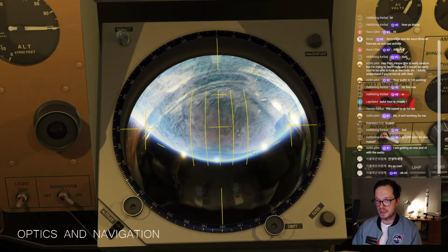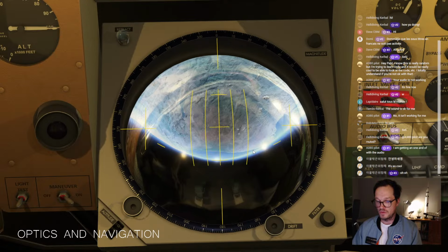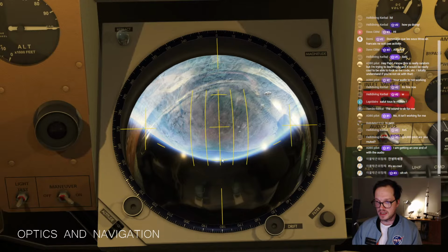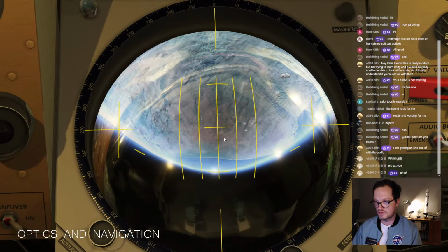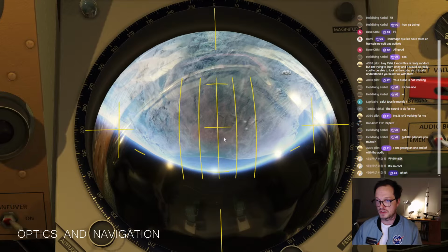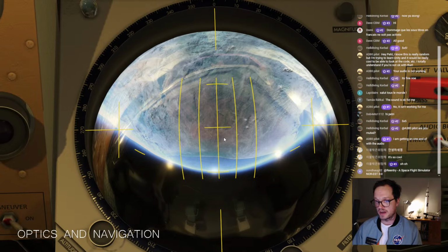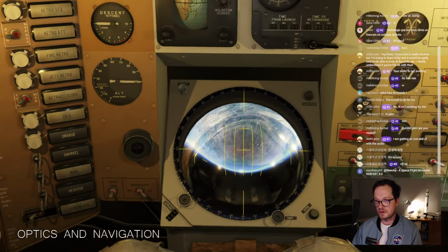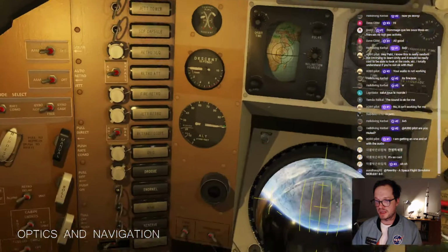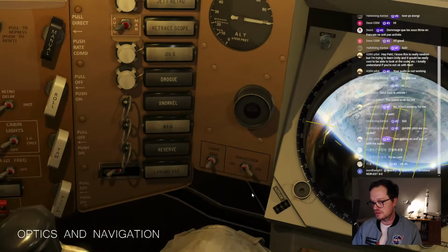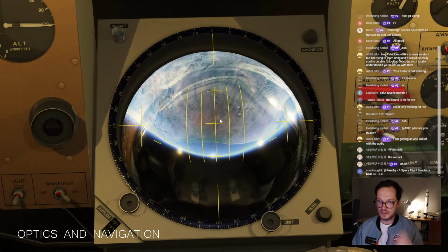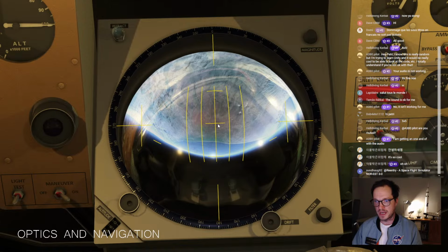So now I know that I was in a level view, and I know that roll was okay and yaw was okay. This means that if I now align this marker with the horizon, I know that I'm in a perfect retrograde attitude, and I can be safe to fire up those engines and return home. So if you have an electrical failure or this indicator fails, the gyros fail for some reason, you can use this method to get into any attitude, so the retrograde attitude.